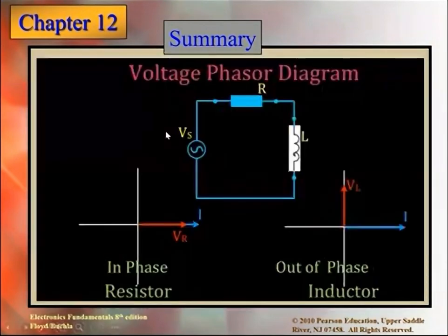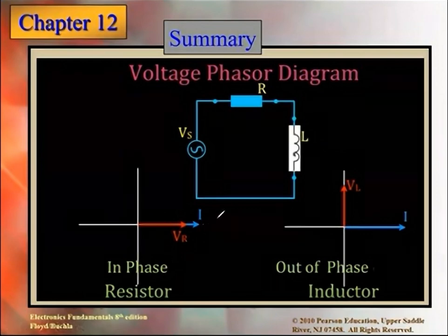So this is the phasor diagram which I already explained to you. Now you can understand it again one more time quickly. You know that I and V are always in phase. So I is here, or we can say VR is here, so VL will be here. They are out of phase by 90 degrees, current and voltage, and VR and I are in phase.